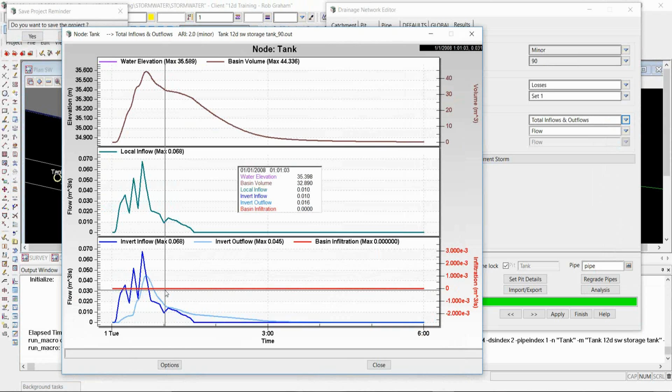One of the things that concerns me when I look at this is this area up in here. This is dead storage. What we're trying to do is limit the outflow. And if I could get my outflow hydrograph to be much steeper in this area, I would not waste the storage, which is the area between the inflow and the outflow curves. So I'm going to go back and revisit this. I'm going to say, what can I do to possibly get rid of this discharge at a much earlier stage so I don't need so much volume?